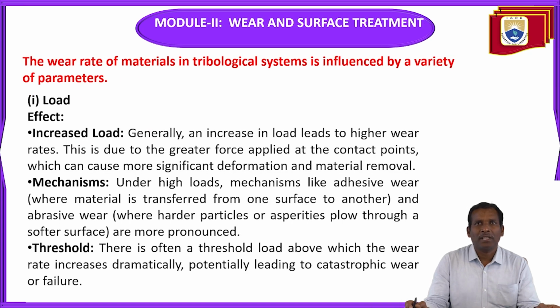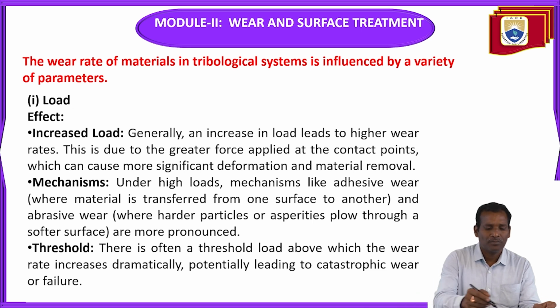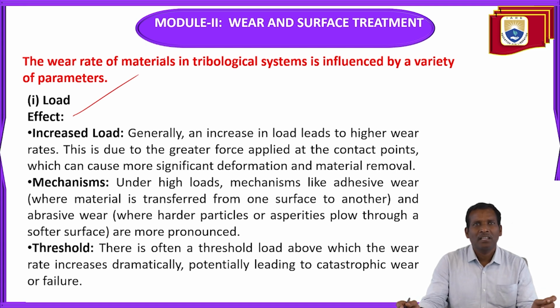The wear rate of materials in tribological systems is influenced by a variety of parameters. One is load. What is this effect? An increase in load generally leads to higher wear rates. This is due to the greater force applied at the contact points, which can cause more significant deformation and material removal. So whenever the load increases, it leads to higher wear rates.